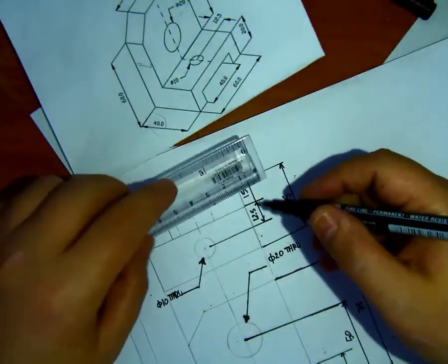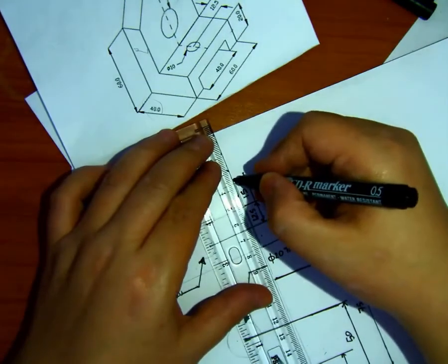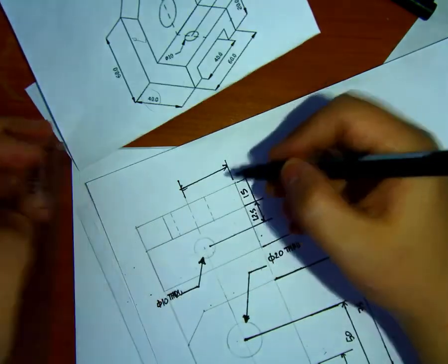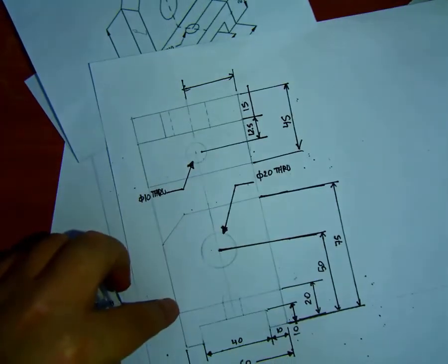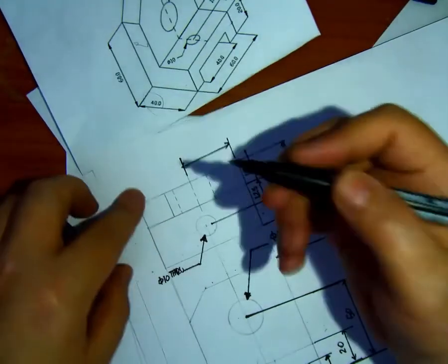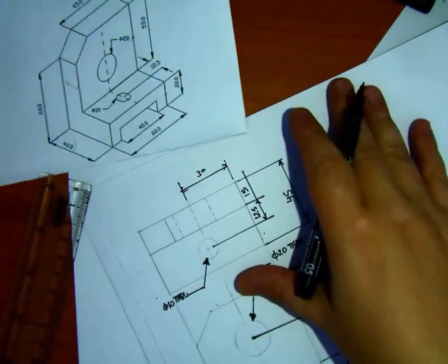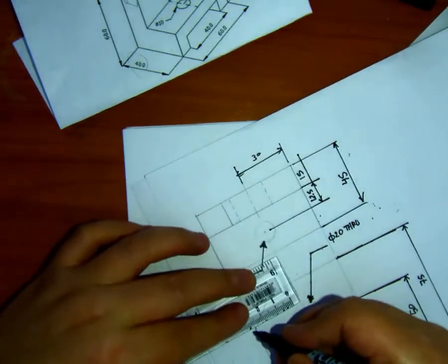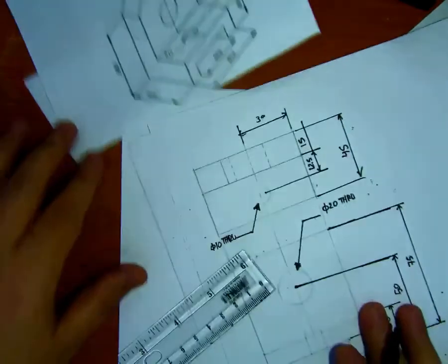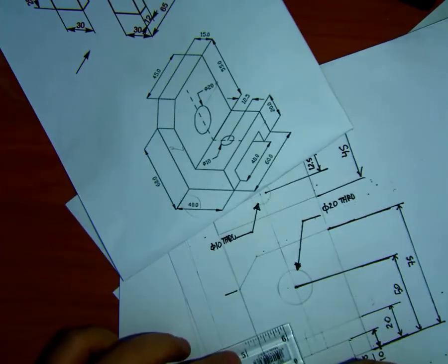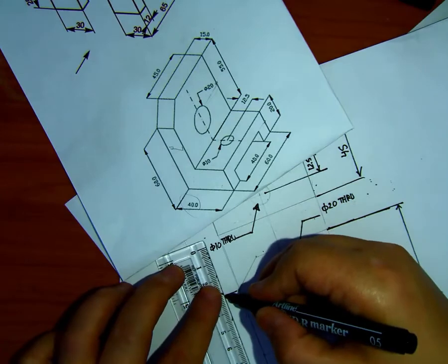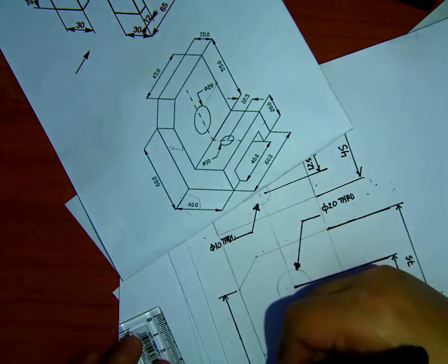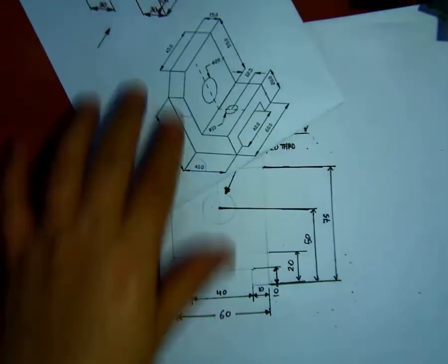You can give the center of the circle, as an example, from this area, from here to here, which is half of this 60. You don't have to do it if it's 30, but it is preferred. Don't forget to add this value from this side, which is 60. See, it is preferred to add all the dimensions from one location.